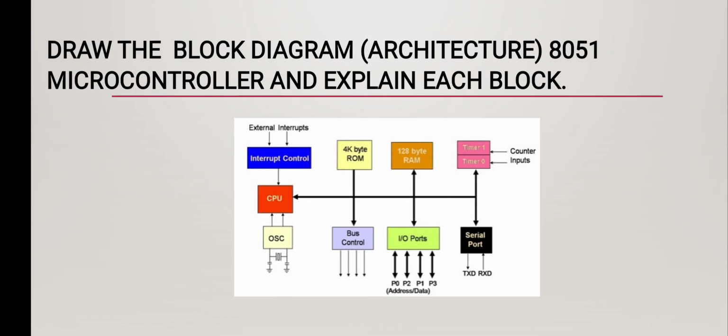Now let us move to the buses. Basically, a bus is a collection of wires which works as a communication channel or medium for the transfer of data. These buses consist of 8 or 16 or more wires of the microcontroller. Thus, these can carry 8 bits or 16 bits simultaneously. Here, two types of buses are shown below: address bus and data bus.